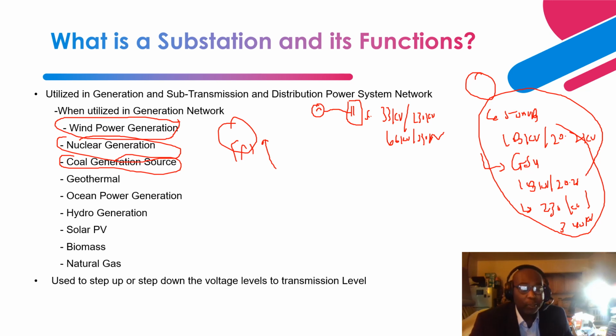The flow of water is achieved by a boiler feed pump motor, which pushes and feeds the boiler with that amount of water. That water is heated by the boiler, through combustion of the coal powder, and the water gains the heat from the boiler.